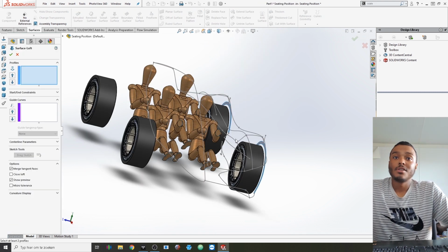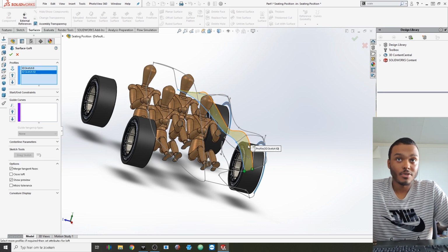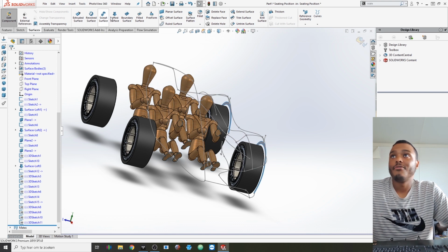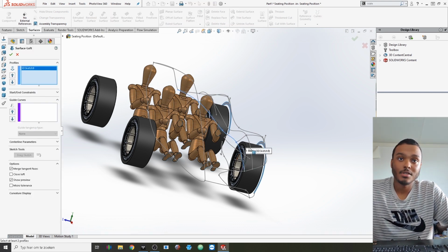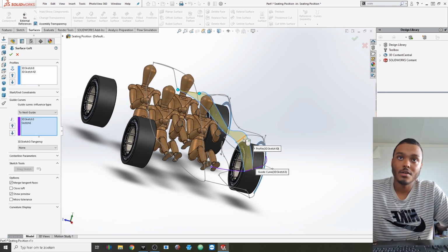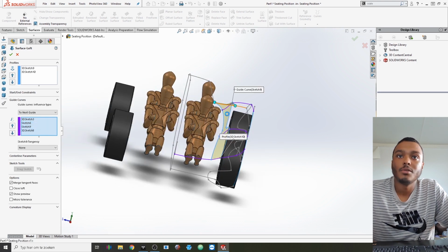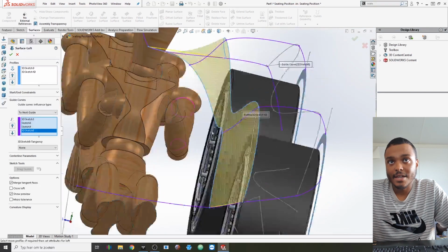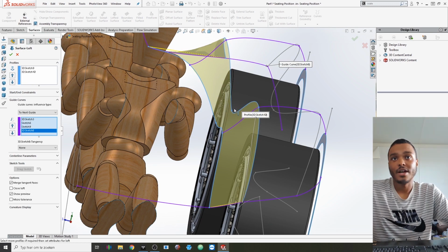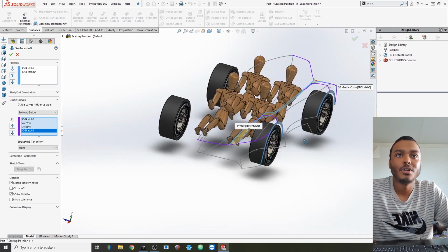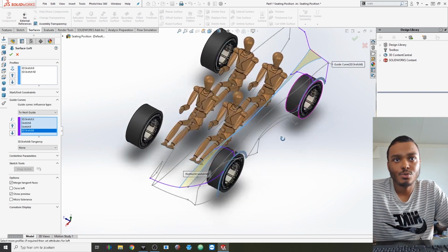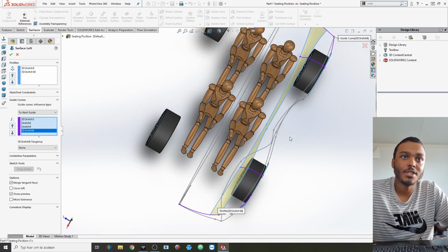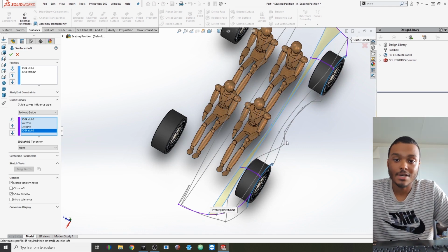So the next thing is to drag the surfaces across from one another and create a surface between them, and that is how simple it is. Within the surface tab, you will have lofted surface, and then you select one, select the other, and then use the guide curve. You have a guide curve right here, one right there, one right there, and one in the back. You need to take a look at it, because sometimes it will create weird indentations in places where you don't have guide curves. So then it will be wise to also put a guide curve right here in the middle, and you could use all of these points right here, if you line them up correctly, to put a nice pattern in there that is exactly what you want it to be.